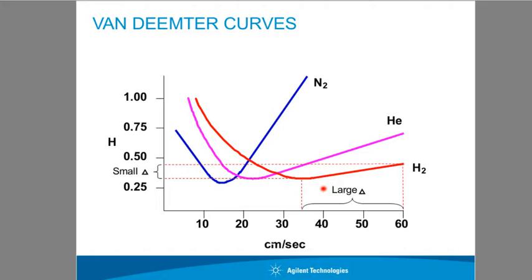Because with the same efficiency, so if you like the resolution that you've had, typically switching from helium to hydrogen, your analysis time drops by a third, and you maintain exactly the same resolution throughout your analysis. So that's one of the benefits with hydrogen. As you can see also, you don't have as much loss of efficiency with going faster either. So it's really, really beneficial that way.